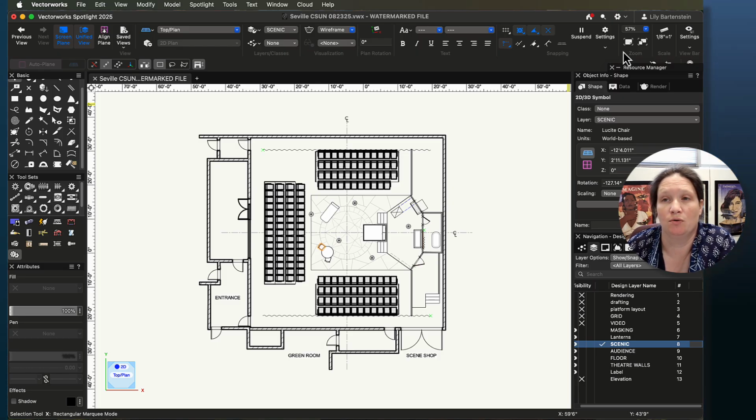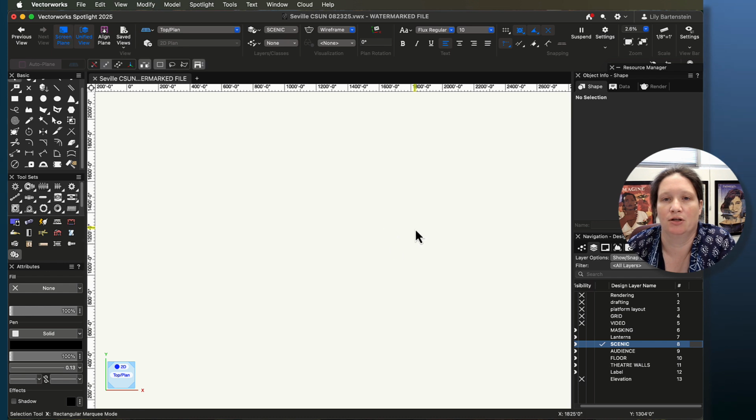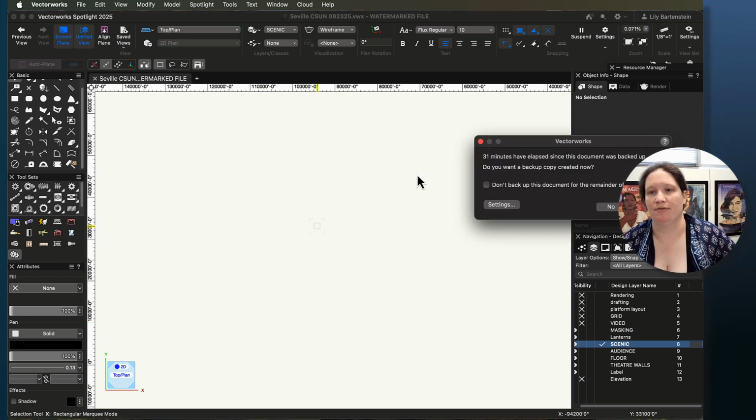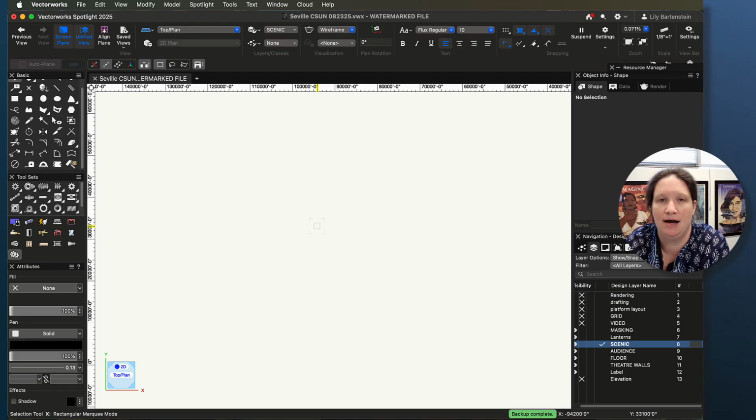The really useful ones here are these two, which are fit to page area and fit to objects, and those are super valuable in the case where something like this happens, right? Where you're like, oh shoot, where did my thing go? That will happen to you with some frequency: I lost the drawing, I'm someplace out in space and I don't have my picture anymore.